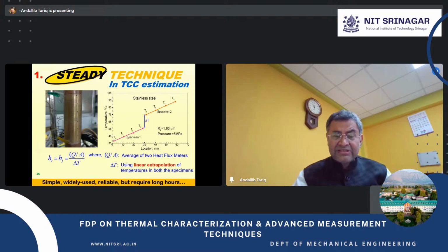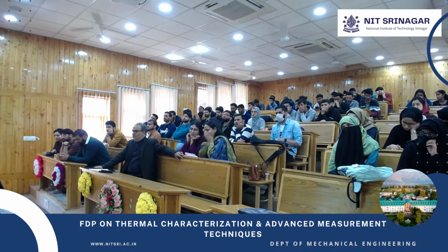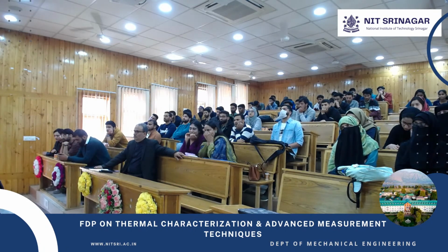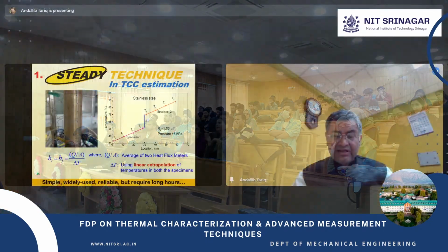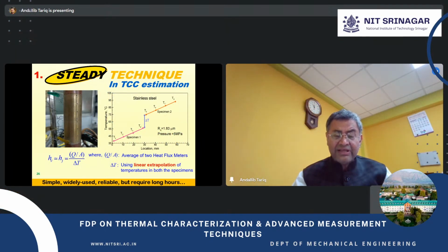We know that across the substance, it will be a linear conduction law, Fourier conduction law, to be extrapolated. So with this extrapolation, we take the actual measurement, specimen 1, specimen 2, for some particular roughness, for some particular pressure with some material. And we repeat every time we change the pressure, or sometimes we change the roughness, sometimes we change the temperature, something like that, and we find out the TCC, the thermal contact conductance.